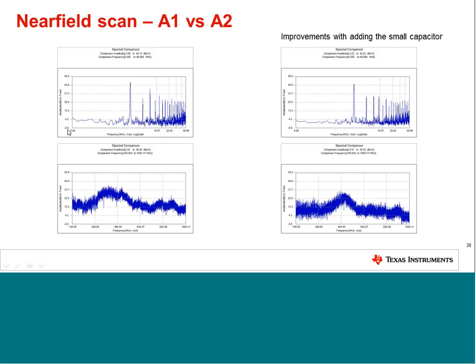And this is the area where the switching frequency is. You have the dominant pulse in the spectrum, and with the capacitor, you have a slight improvement here, even at the switching frequency, and even using 470 picofarad for a 2 megahertz signal here.